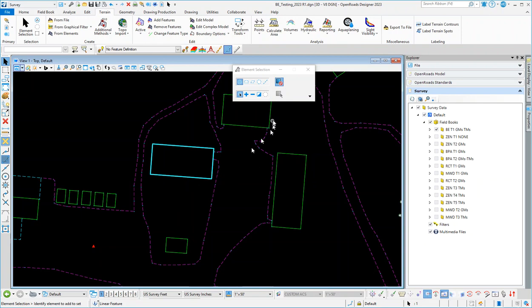This is basically the on-off switch if you want to view them. If you're not seeing them, you want to verify whether this is turned on or off. When it's off, it doesn't have the box around it. When it's on, you'll see that background there. So when the disable handles button is on, they are disabled, and you don't see the manipulators. When that's off, then you see the manipulators.